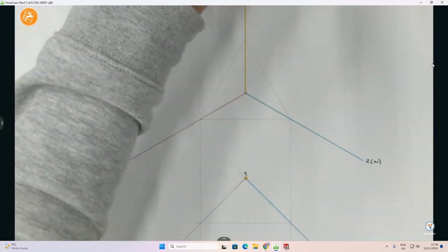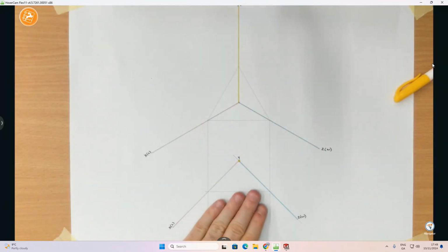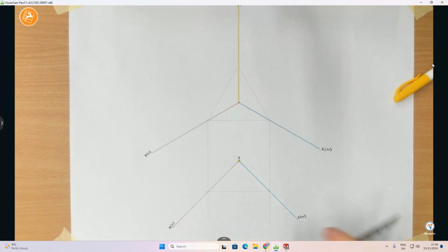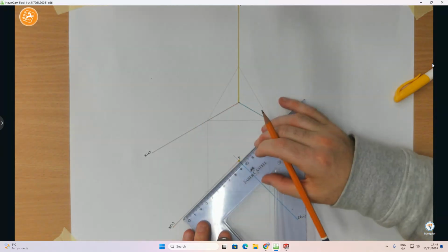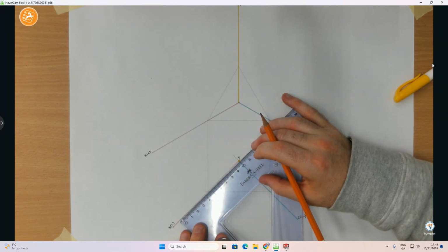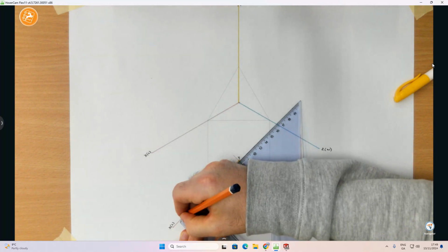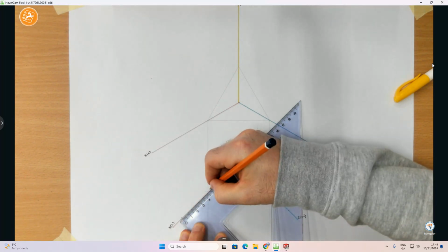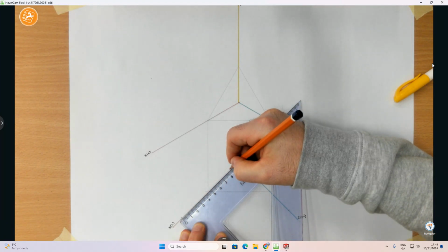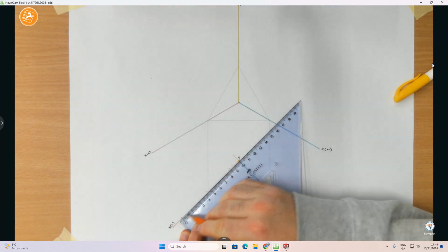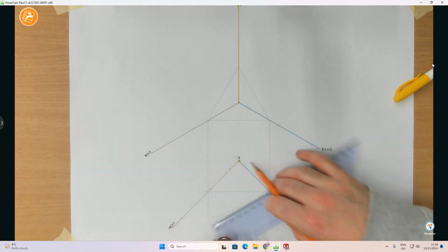So in my plan view, this is going to be where I'm drawing my plan. Okay, this is the horizontal plane. All my lengths are going out along this one. So I have a length of 100. Hopefully it just fits on my page. Quite hard to fit an A3 page, so I'm going to measure down 100. And while I'm at it, I'm going to measure up 50 and an additional 35, so there's my 50, 35. So there's my lengths.